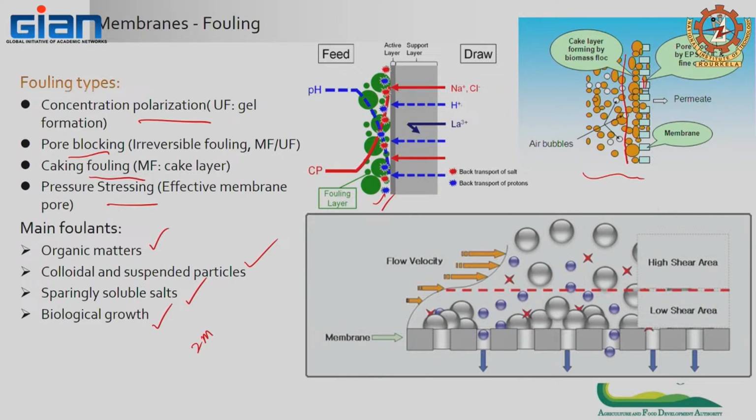So, here also again new technologies are used to improve the membrane filtration processes by using ultrasonics or techniques to clean those membranes, and how often you need to replace the membrane. It is not that a membrane once installed can be used forever. They also have a specific life of usage. Whenever you talk about membranes, think about your tea strainer, how long you can use it. So, that is the issue with membrane fouling.